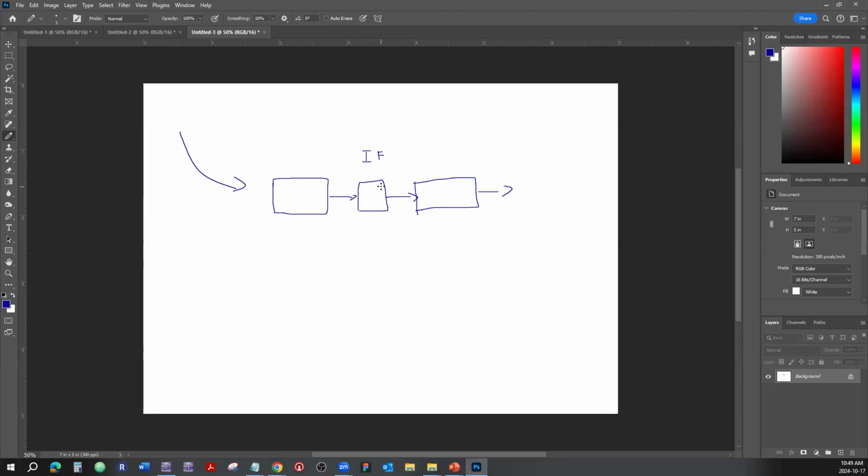Remember we did the frequency multiplier? It has something to do with that in order to accomplish the intermediate frequency. Why would we call it the intermediate frequency? It's because it is between the receiving frequency and the rest of the circuitry, so it's an intermediate type of situation. So somebody called it intermediate frequency. It still has a carrier, but the carrier is 455.